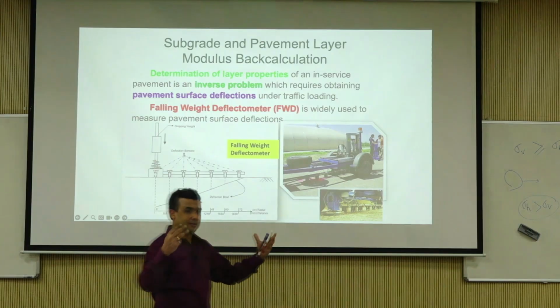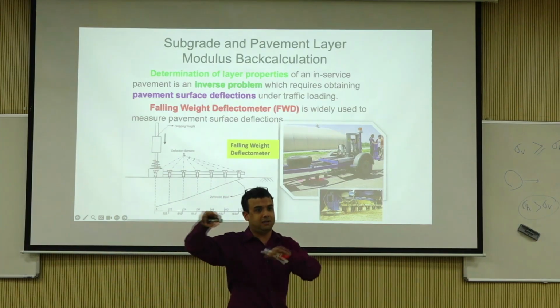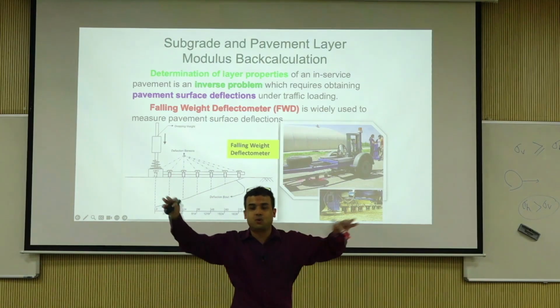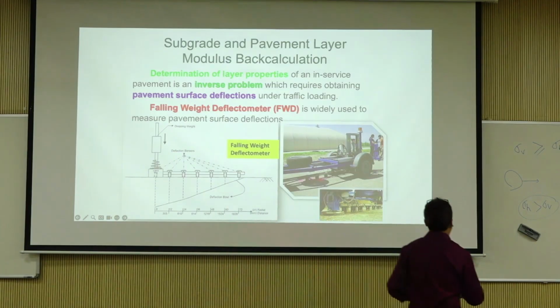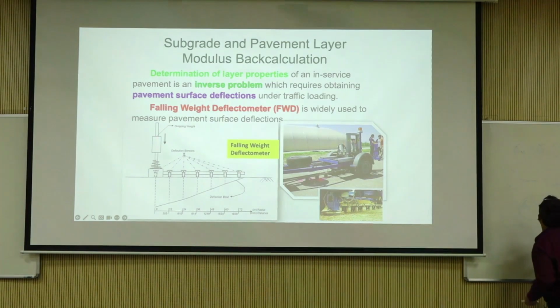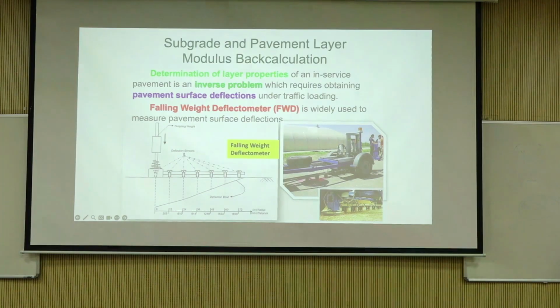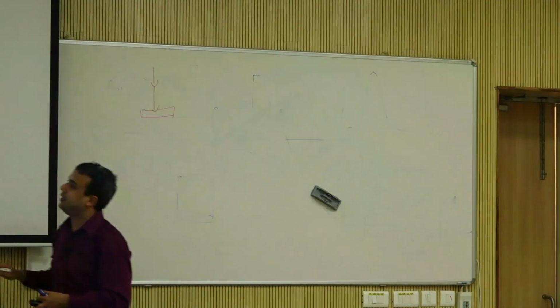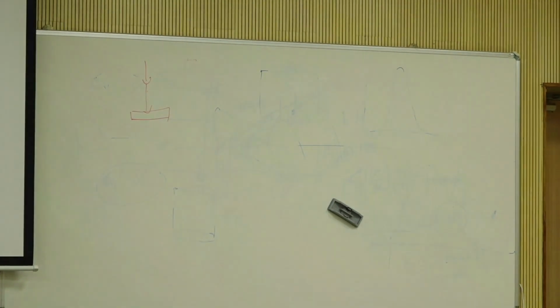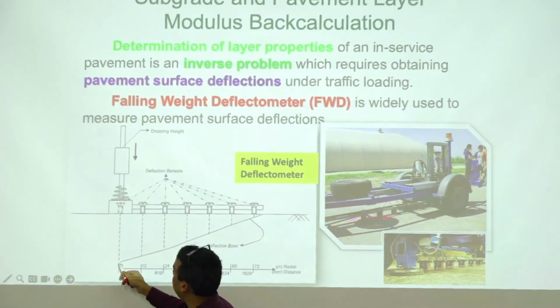A very good road, it's going to distribute the deflections evenly, and it's going to have what is known as a wider deflection basin and stuff, right? So we won't talk about that. So falling weight deflectometer is a pulsed load application. It's an impulse loading which is applied by dropping a load basically that drops here, and then it applies some kind of a pulse, and then you measure, and then obviously underneath the load the deflection is the maximum.